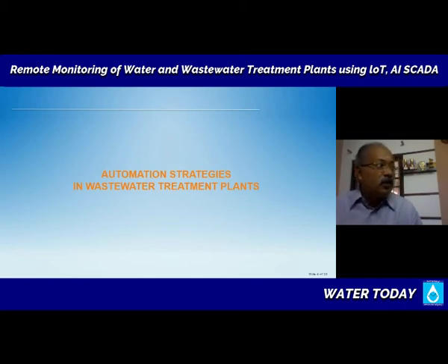If there is any risk of acid flow and these sort of things, then chemically resistant material is used for sensor construction. For example, Teflon, PTFE, that's a material with very good chemical resistance. Sensors can be made with PTFE construction, which gives you very good life in an industrial environment. Yes, to answer your question, it has been very widely used in effluent treatment plants, and it can give you excellent performance without any problem. Only thing is the sensor material has to be carefully considered. So I hope that answers your question.